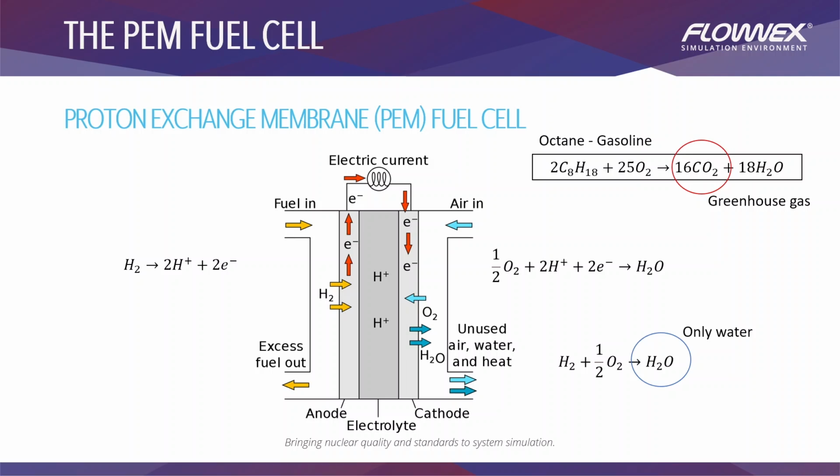However, operating this fuel cell comes with quite a few challenges. One being that the membrane must be hydrated properly to allow for ions to conduct. But if water condenses and forms droplets, it can restrict the flow channels and reduce the ionic conductivity. This is called flooding. So essentially, for the PEM fuel cell to perform optimally, the system needs to be designed such that the electrolyte is well humidified. This means that water management is extremely important during the operation of the fuel cell.